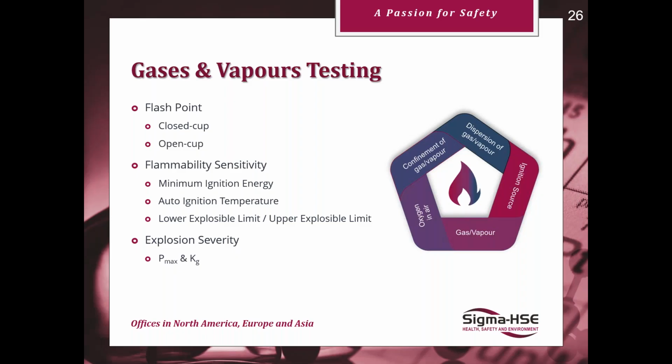Starting off then, we have flashpoint testing. There's typically two variations of this test. We have the closed and open variations, and it's usually the closed cup apparatus which is preferred because it tends to give a bit more of a conservative value.